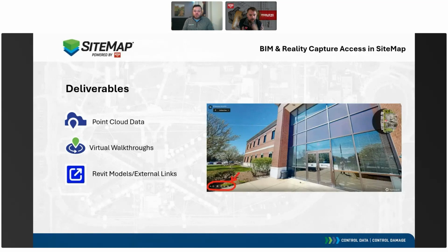Now, if you need to model from that data, if you need a more dense point cloud, something that's really accurate, we can utilize different laser scanning equipment in order to model those pipes that are 1 inch or larger, 2 inch or larger, those structural elements, and give you a higher level of detail, a floor plan, and have it be BOMA compliant from the measurements that we're taking. And that can also turn into a virtual tour. So it actually has multiple benefits beyond just being accurate.